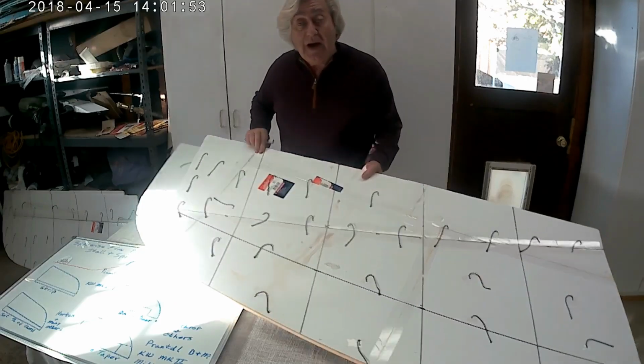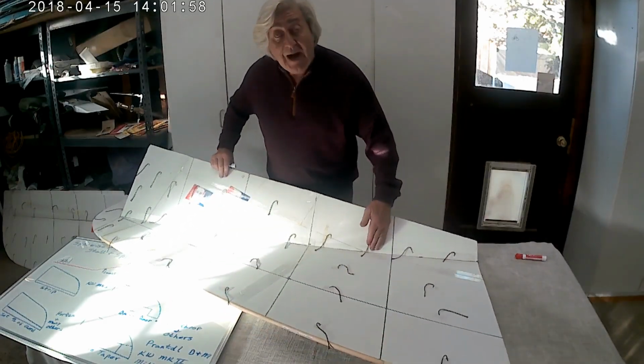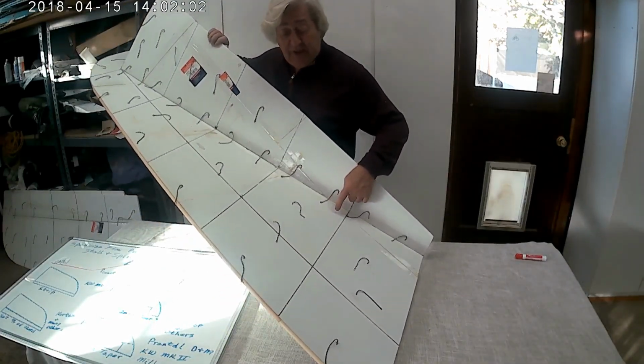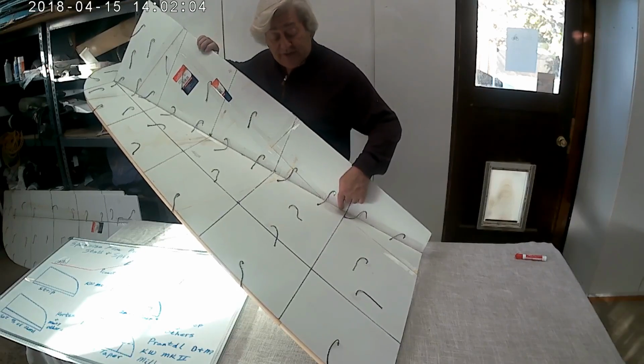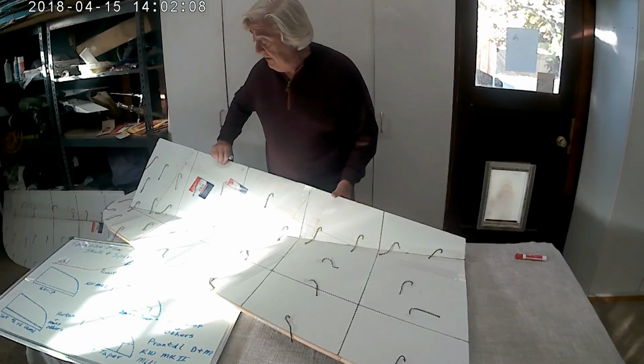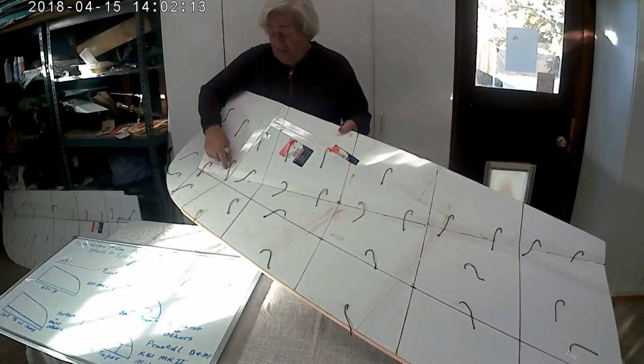And that's why on this elevon inboard we got spanwise flow, because when you're way back here away from the leading edge, your momentum's really low. You've lost a lot of velocity. You no longer have enough momentum to get up the hill. Out here, you got plenty of speed, plenty of momentum, and you can get up this hill.